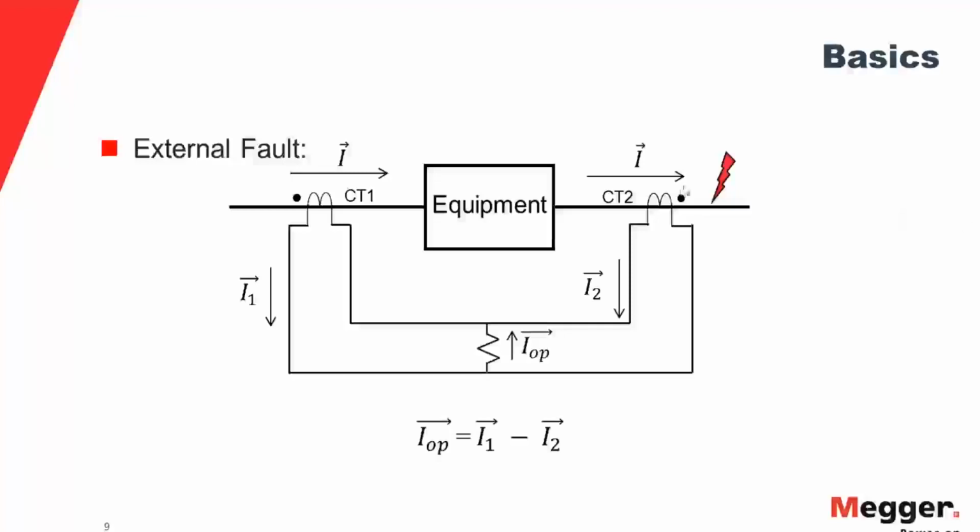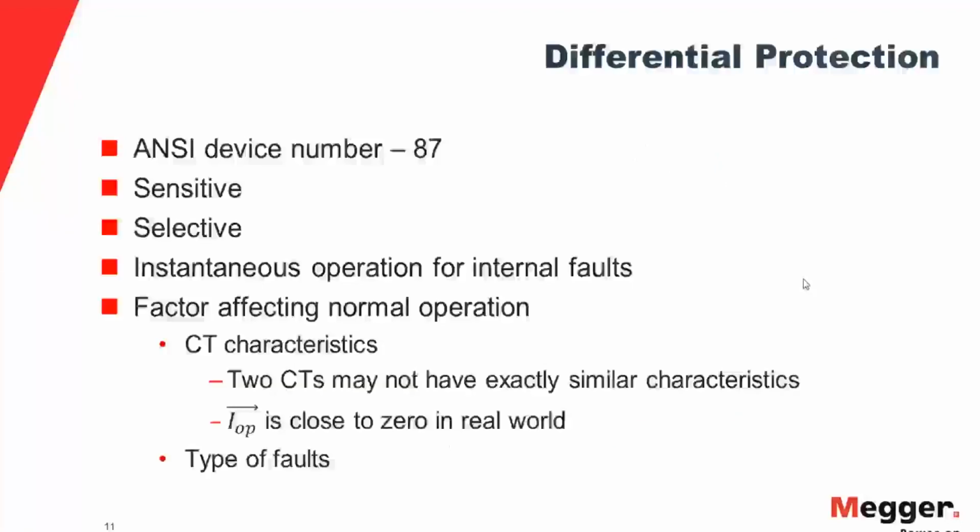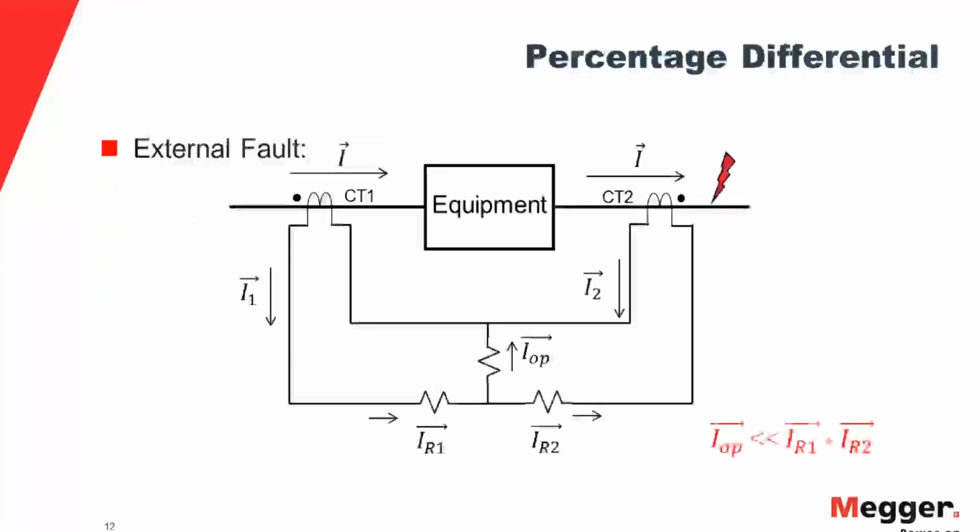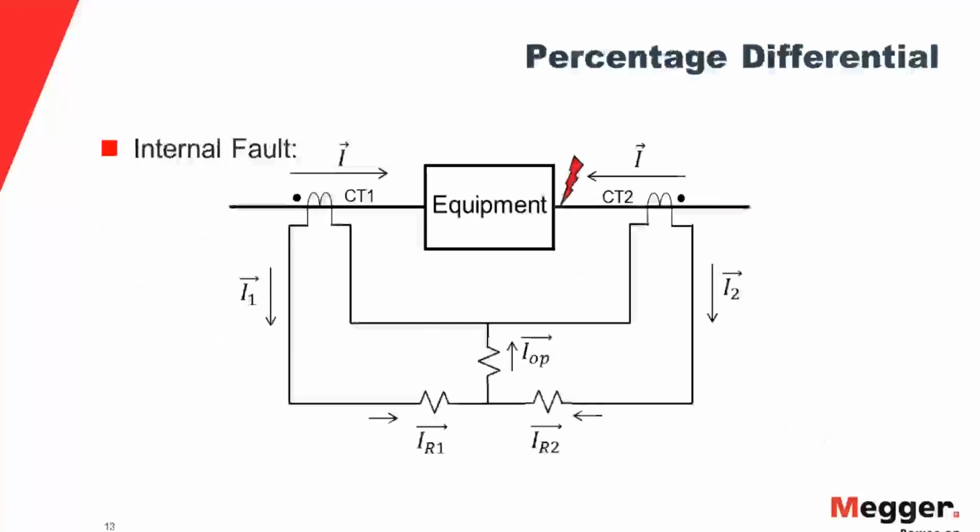So that's how you detect a fault inside a transformer, as opposed to an overload that would detect a fault in just one direction, that current's flowing through it. The cancellation of the currents helps you restrain through faults, line faults, or downstream faults from operating the transformer differential. But any faults between the CTs, they sum together, you have a very high amount of operating current, and you can clear it for that internal fault.